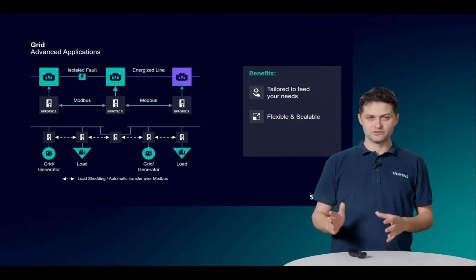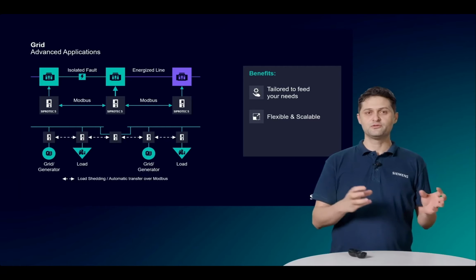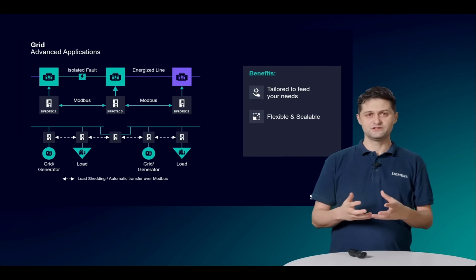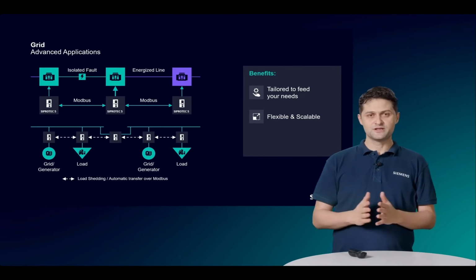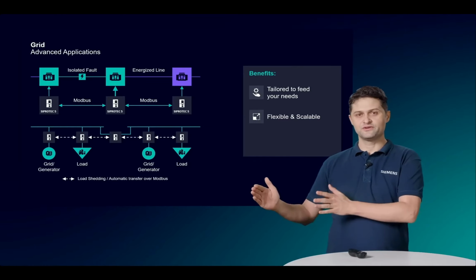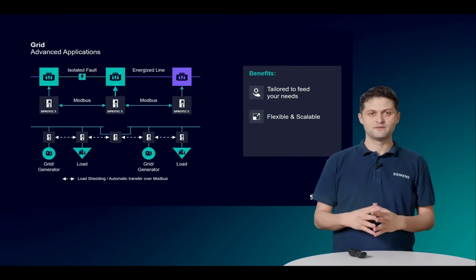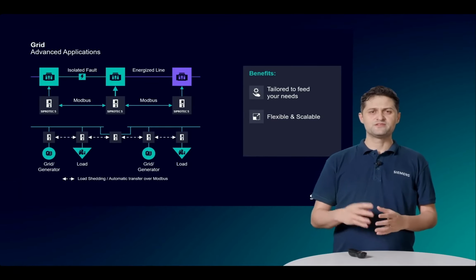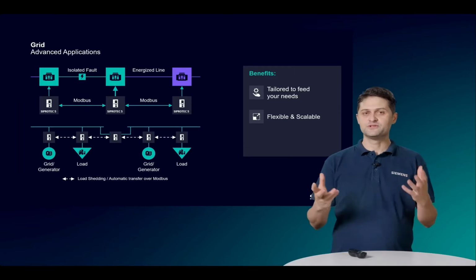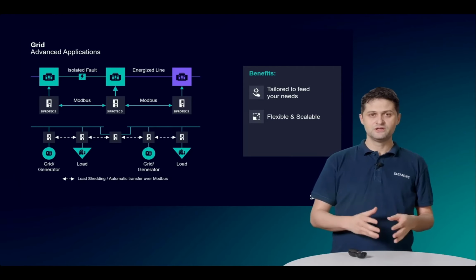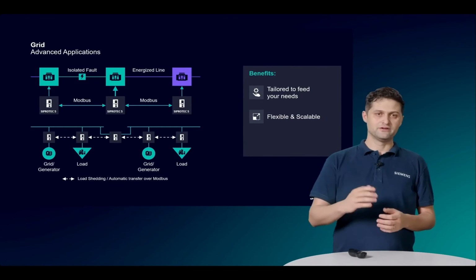are installed as reclosers. Such SIPROTEC 5-based reclosers can collect different fault information from the fault passage indicators or other reclosers, process it and define the fault direction, and issue isolation commands to the recloser to isolate the faulted path of the grid, and the rest of the distribution line can be re-energized in minutes, sometimes even in seconds. Such applications provide faster recovery time so that consumers won't be left de-energized unnecessarily, and also precise information about the location of the fault, so the field personnel can reach the exact location and maintain the faulty area.